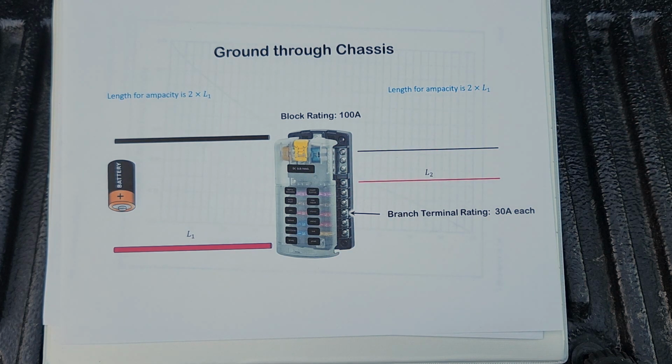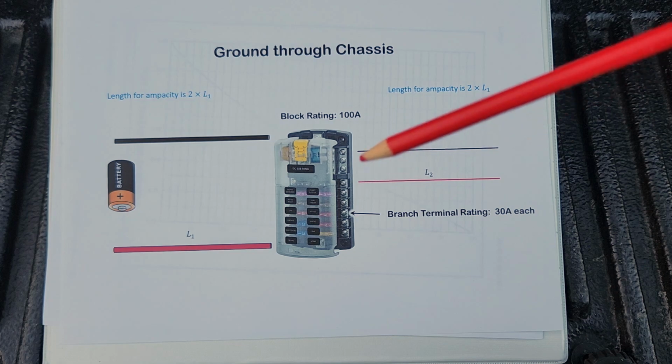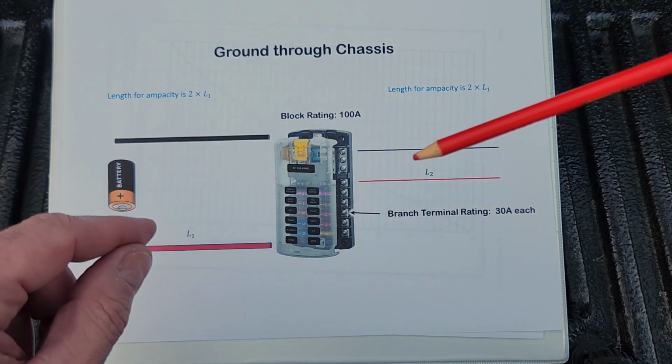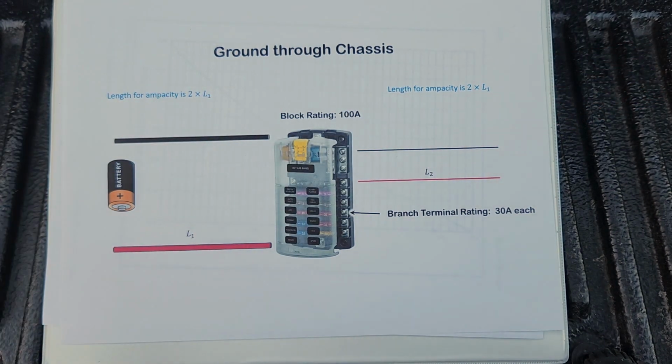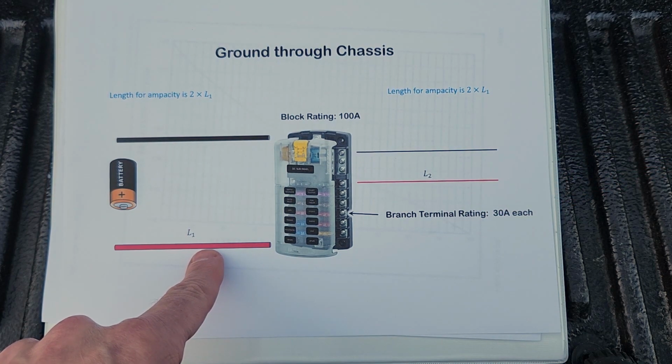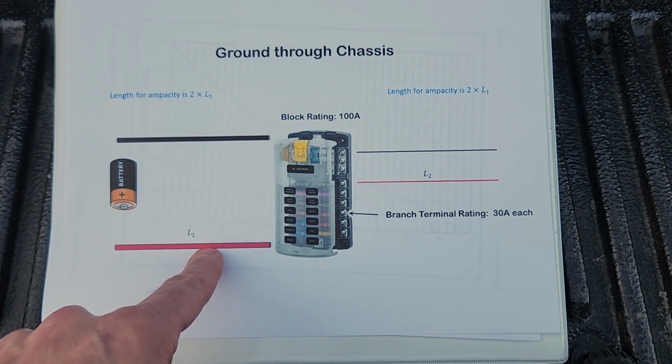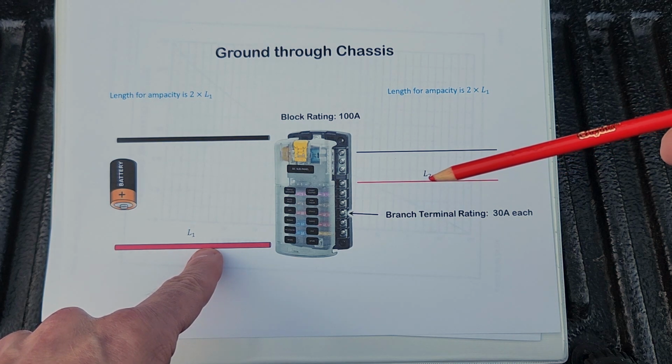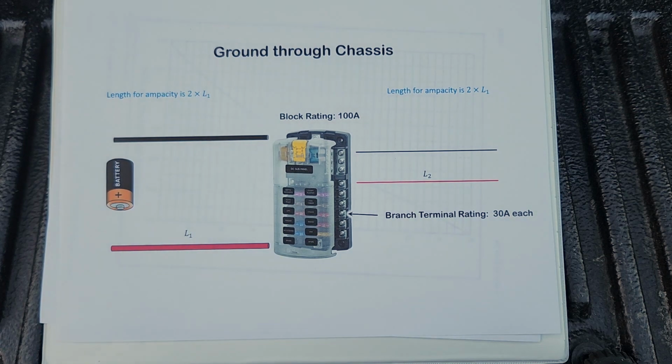And I created a spreadsheet that did that for one of my setups in a camper. And what I discovered was you can mostly treat the load side and the supply side separately. There were some corner cases, some oddballs, where if I decrease the size of the supply side by one gauge, like 6 gauge to 8 gauge, the size of this wire might have to go up a little bit to the next larger wire.